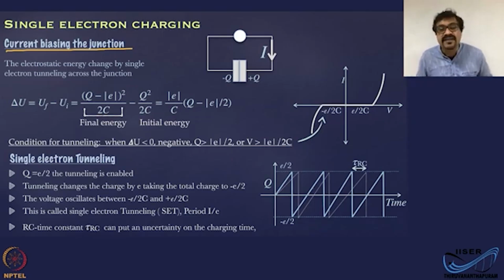One of the practical ways to make a current source from a voltage source is you just attach a very large resistor in series with the voltage source, then it becomes a current source. Because then the resistor which is in series is going to decide the current. That is going to dominate the whole transport. But of course, you have to make sure that the value of the resistance is really large compared to other resistive elements in the circuit. Then only that's going to dominate the transport. All right.